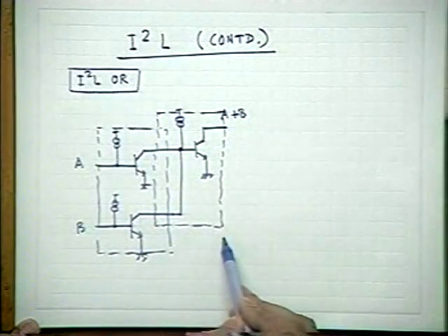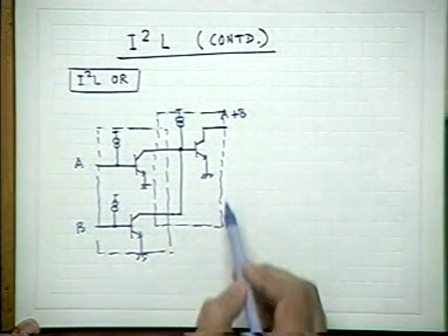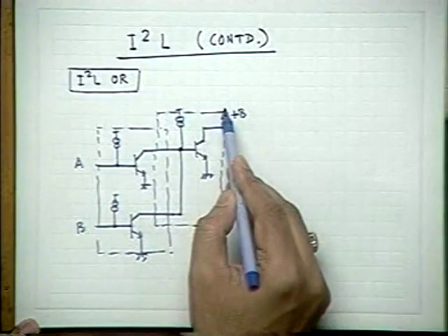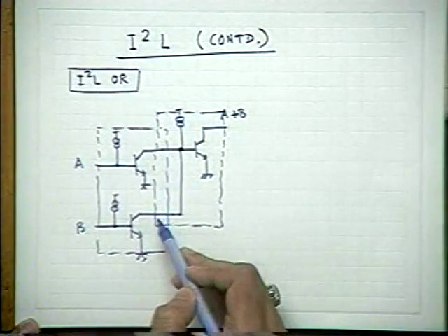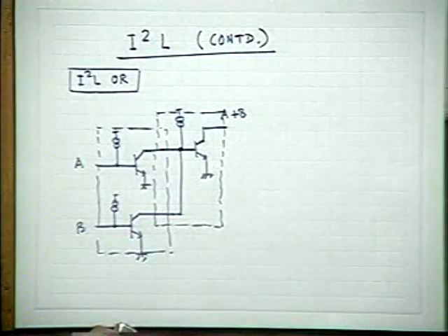Whereas this block shows an AND gate, because we have wired the input. Only thing is you have applied the complement of the inputs. So the simple thing is, if you want to create an OR gate, you invert the inputs and then wire them and pass it through an inverter.